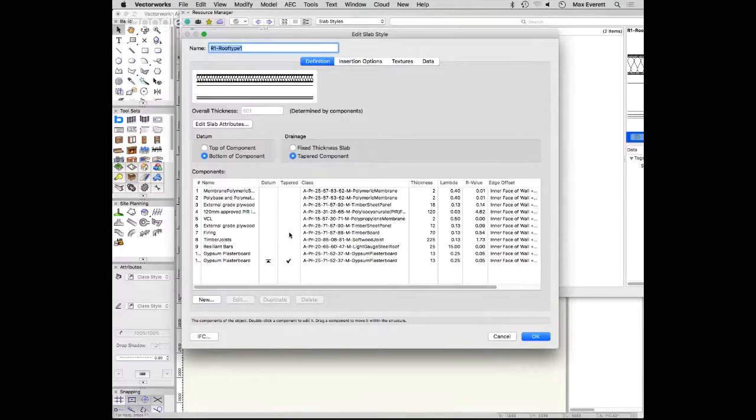So you might have tapered insulation, so you click it on the tapered insulation, for example. Or if you're having fairings, you might have a component that's called fairings, and then you tick it. There we go, I've got fairings. So I'm going to keep my insulation at 120 and tick the fairings to be tapered rather than the actual insulation. Tapered insulation is expensive.